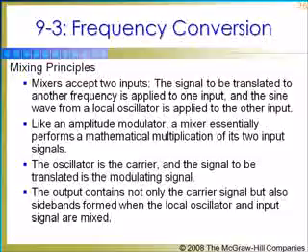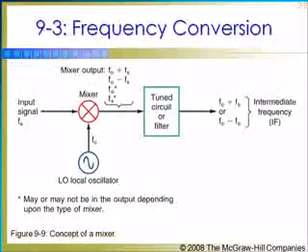When translating to a higher frequency, the upper sideband or sum signal is chosen. Again, the local oscillator frequency determines what the new higher frequency will be. A tuned circuit or filter is used at the output of the mixer to select the desired signal and reject all the others. Here is the schematic diagram of a mixer circuit.